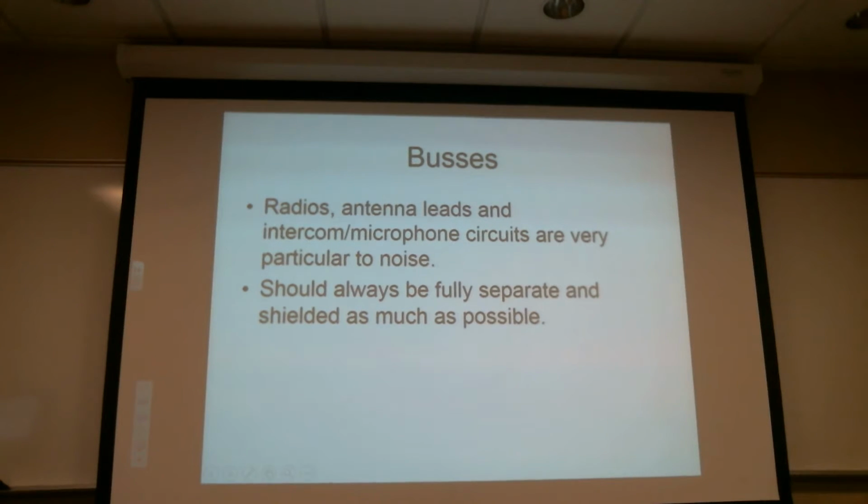If you can take it back to the radio. In fact, some radios actually have a special audio ground. Don't attach it to anything else. One of the Sigtronics intercoms has that, the SPA 400, and I forget which model, but they have the main power ground, and then they have an audio ground. All Garmins now have a little stud on the back of each connector where you're supposed to connect the shield. That stud is the one spot. Don't put it anywhere else. And that's the reason for that, because there's all kinds of noise happening.